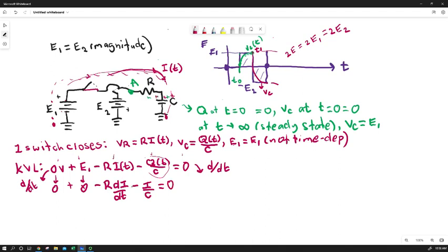And I haven't written I as a function of t because we already know those are changing with time. So we can rearrange this. For those of you who might be taking some math in the future, this is known as a variable separable differential equation. It's the easiest one to solve because all we do is rearrange things and we get all of the I-dependent terms together. So we're saying 1 over the current times the rate of change of current with respect to itself is equal to negative the rate of change of time, and we end up with R and C in the denominator.